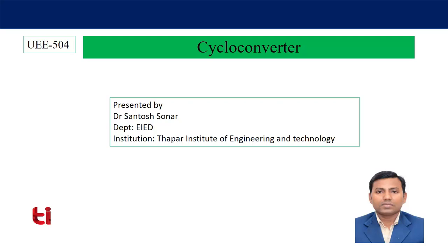That is, from AC you first convert it to DC using rectifier, then DC voltage is converted to AC using inverter at different frequency. As the function of inverter is to give you control over output voltage as well as frequency. If you want more output voltage, then at the rectification stage you can use DC to DC boost converter.